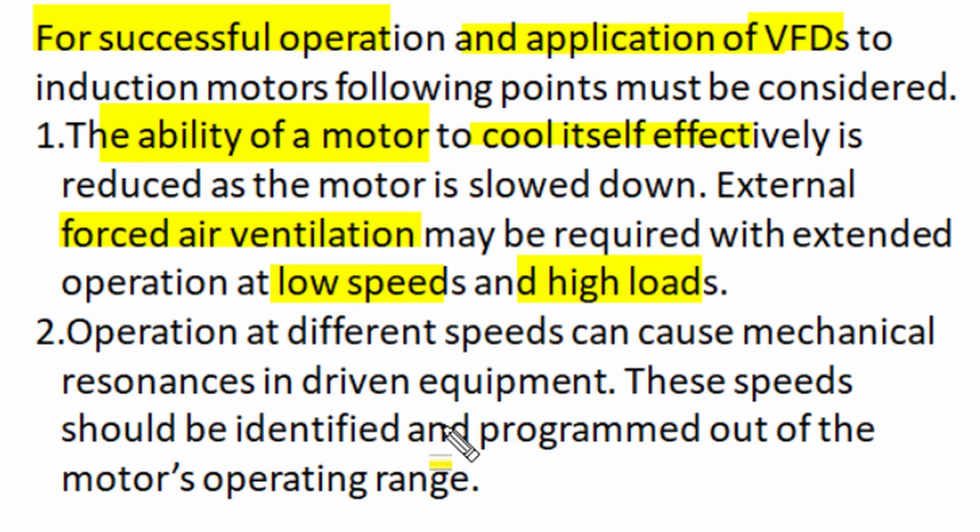When a motor is operated on continuously varying frequency, the mechanical parts attached to the driven system may cause some sort of mechanical resonance at some specific reduced speed conditions. These speeds, which produce resonance and cause excessive vibration and noise in the mechanical driven equipment, should be identified, and during reduced speed operation with varying frequencies, we should avoid operating the motor at those frequencies. The identified frequencies must be programmed out by the controller so that the motor does not get such a troublesome condition of mechanical resonance in driven components.